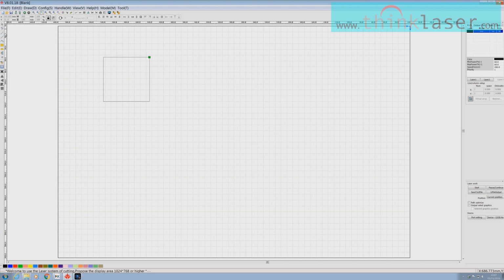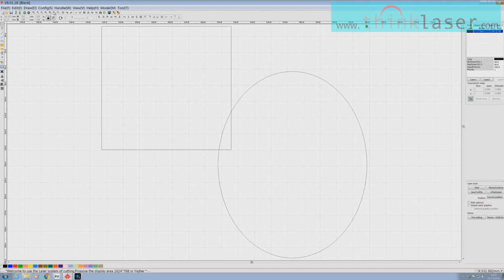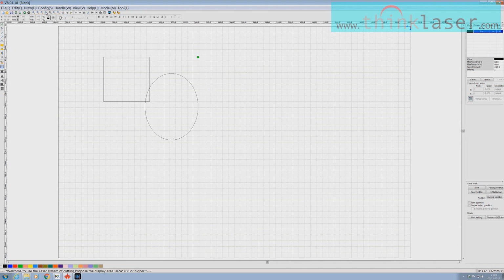But if I draw a circle on here as well, we shall be able to demonstrate what I mean. So if we do the show all, which is that one, view all, it just puts all of the objects that are there onto the screen. Okay, the middle one sets it back to normal, and then we have the opportunity of show selected data.